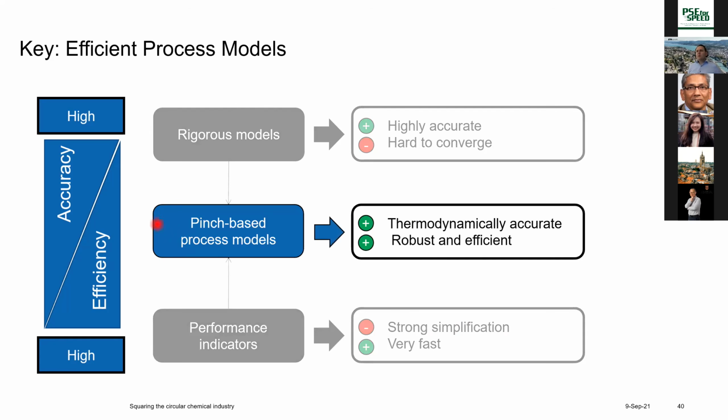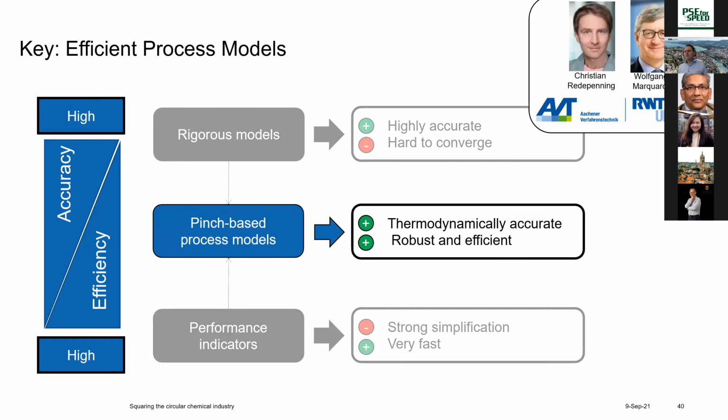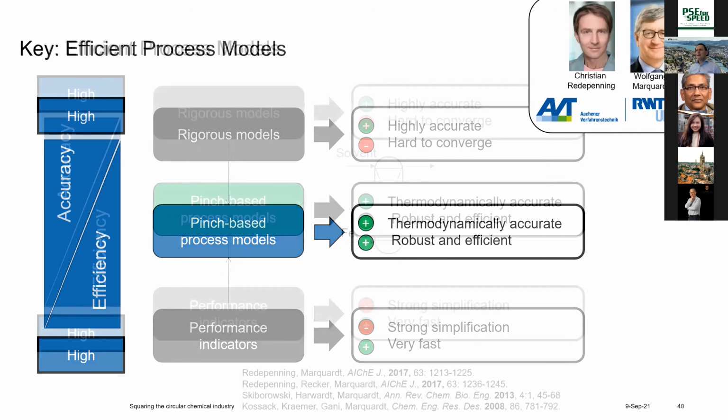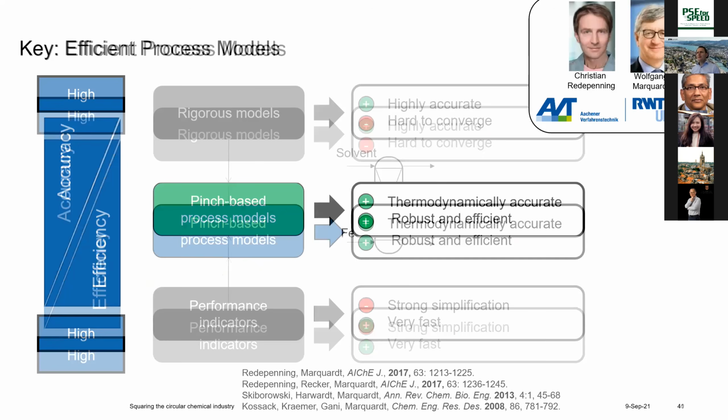And what we employ in our framework are so-called pinch-based process models that employ the full thermodynamic information, but they are very robust and efficient. And what's a nice thing, they have been developed in the group of my PhD supervisor, Wolfgang Marquardt. And I will just spend a very brief slide on them. What are these models? They are pinch-based.